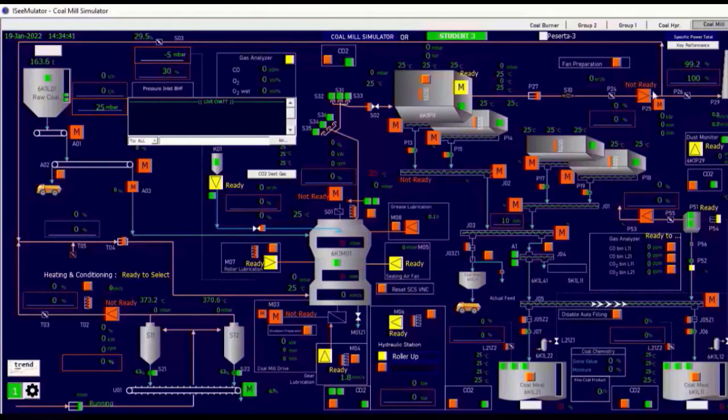The material from the mill then goes up to the separator to separate the coarse and fine materials. The coarse returns to the grinding mill, and the finer becomes the product. Fine material from the separator enters the dust collector. The fine coal material that is filtered in the dust collector becomes a product. Then the fine coal product through the screw conveyor is inserted into the fine coal bin 1 or into the fine coal bin 2. Furthermore, the hot gas used to operate the coal mill is taken from the combustion residue from the kiln system. You can see the temperature that comes out of the topmost preheater cyclone, and we can take it or it can be used for coal mill operations.